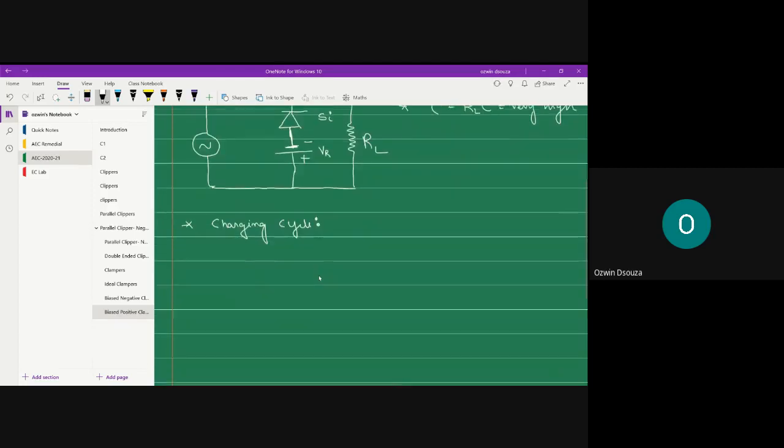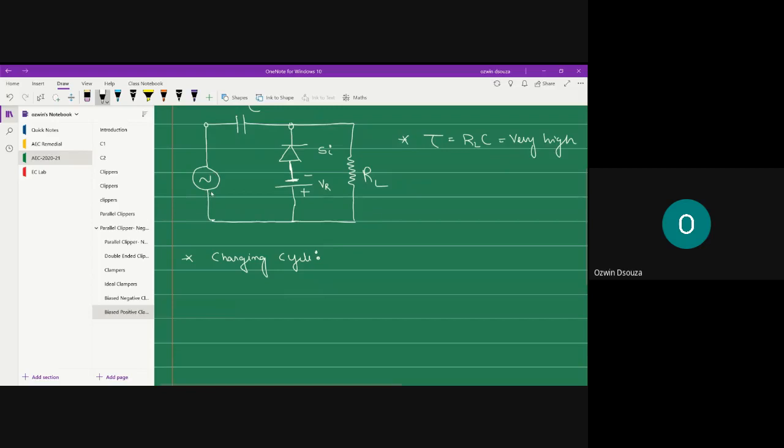What you have to do is identify the half cycle which is going to forward bias the diode. If the diode gets forward biased, the capacitor is going to get charged. The diode gets forward biased in this direction, isn't it? In the anti-clockwise direction. Now, in order to have the current flow in the anti-clockwise direction, you must consider the negative half cycle of the input.